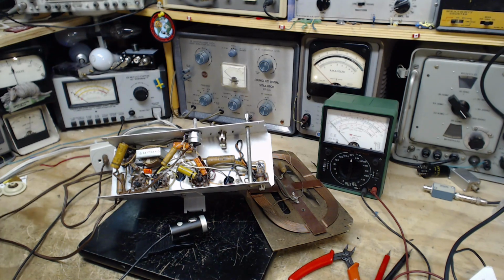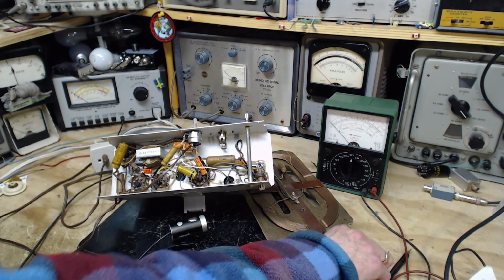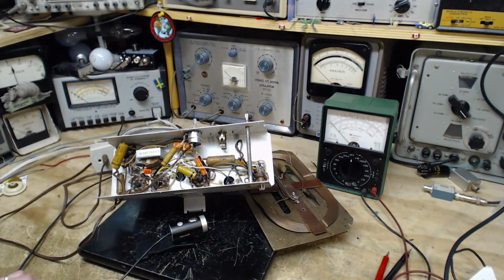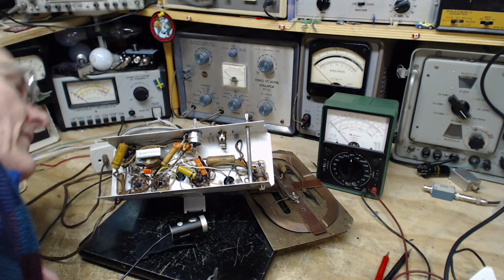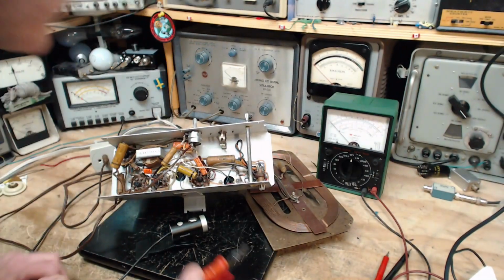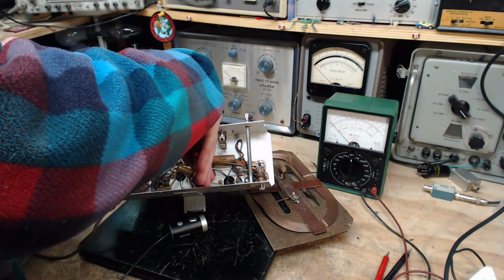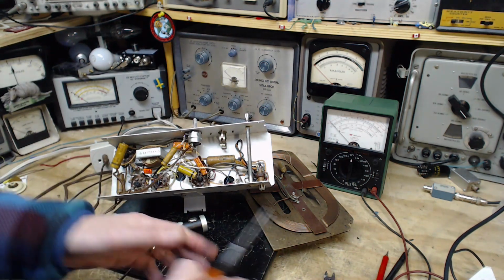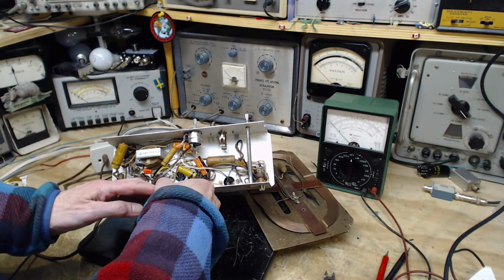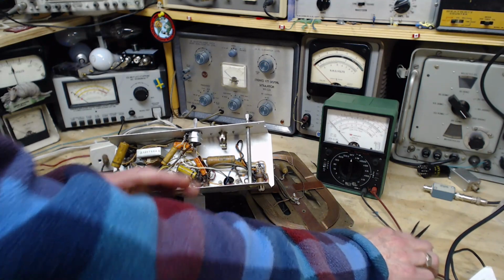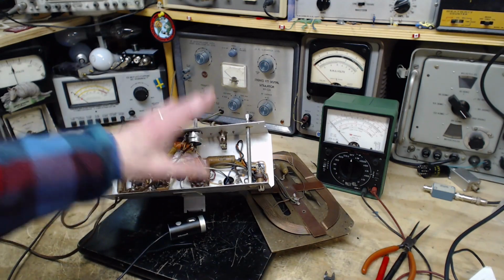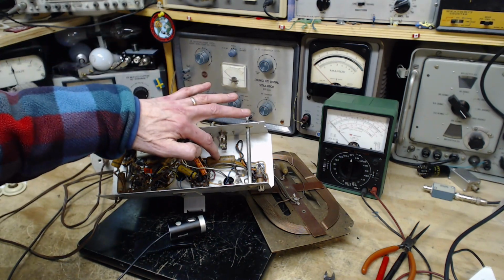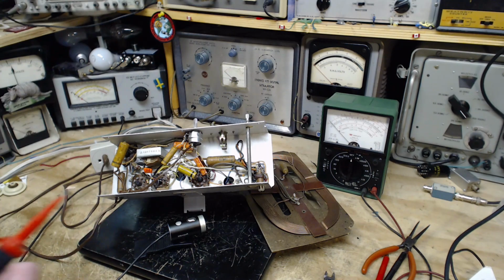Okay, I'm going to cut that resistor out. Very close to shorting against another terminal, but it didn't. Okay, I'm going to move it out of the way a little bit. Good. Can't reconnect. So now the resistor's gone. The only thing connecting the chassis to the radio's B- bus, if you like, is this capacitor. So anything we measure has to do with that capacitor now.